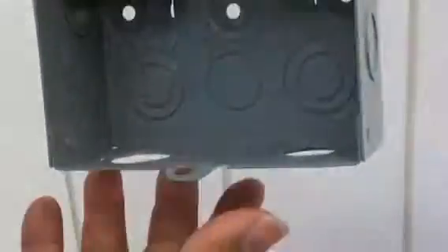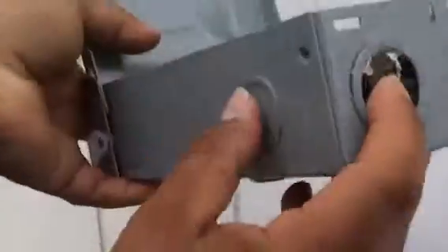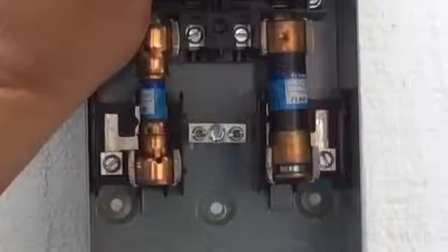These boxes are secured to the wall by these holes, and then you have your knockouts here on the bottom and on the sides where your conduit would come in. You have them also on the back, so if you put it on the wall, your wire could be coming through the hole here into the box, and you would hook it up to your terminals. Then you would have your conduit, seal tight, EMT, rigid, coming out to your equipment or to whatever loads you needed.